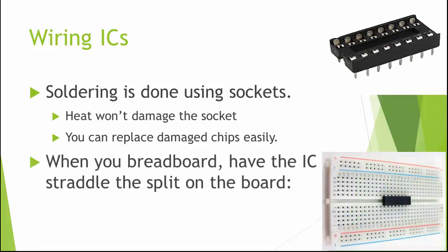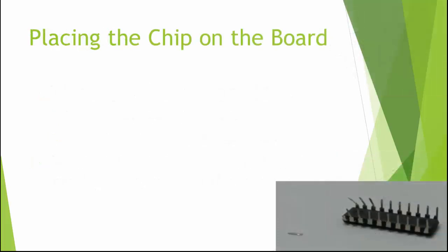In a breadboard, you can simply insert the integrated circuit directly onto the breadboard. And what you do is, this is what the purpose is of this split across the center of the breadboard. And then if you use that location, slide that integrated circuit into place there. Each of the individual pins, you have four ways to connect to each of the individual pins on your integrated circuit. You can go ahead and do that very simply.